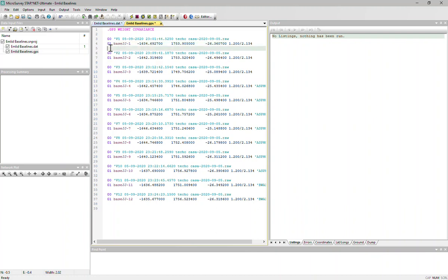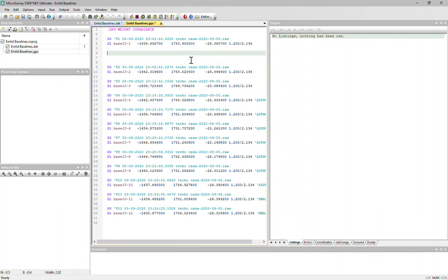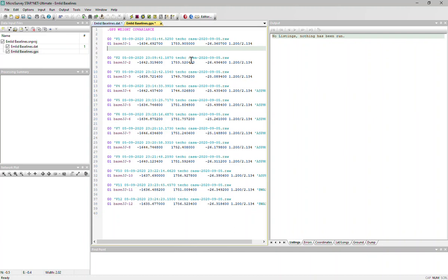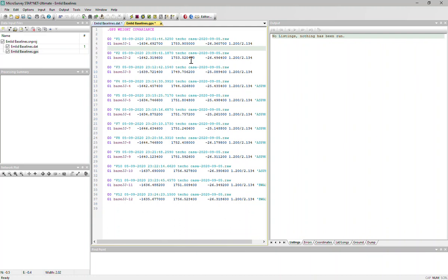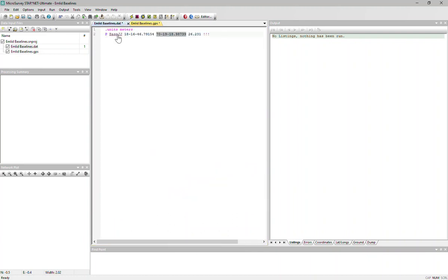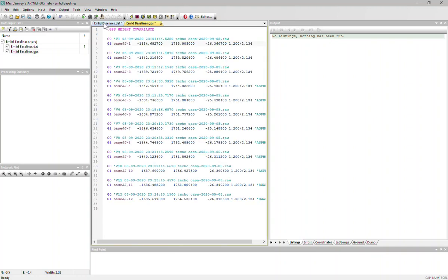Okay, and then what you'll also find is with most receivers, you'll see that there's a G2 and a G3 line, and they in fact give you weighting for each of the vectors. Those items are missing because the Emlid device does not compute that weighting information. Now let me just make sure, so I've got base JJ with capital J there, and I called it capital B base. Let's make that lowercase base. Okay, so these 2 files together will be able to compute the positions of each of these points once we've allowed it to weight the positions.